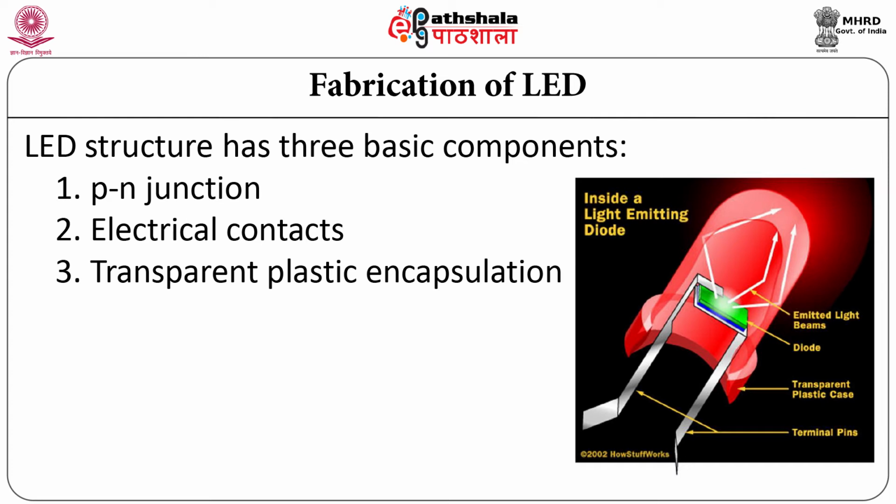The major part of the structure is the PN junction. Active films of the LED structure are normally grown epitaxially, often by liquid phase or vapor phase epitaxy. Common substrates used are compounds of gallium, arsenic and phosphorus. The PN junction can be created by either impurity diffusion, ion implantation, or it can be incorporated during the epitaxial growth phase.